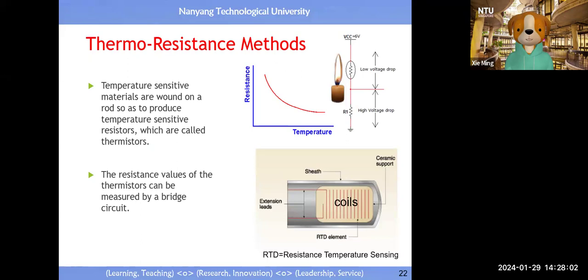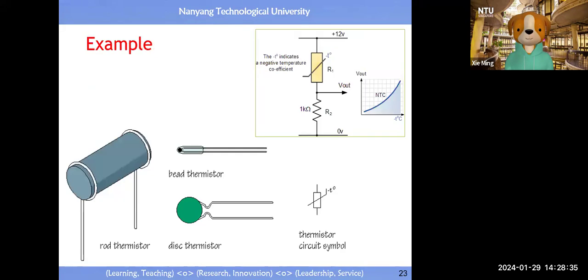So in the video, the very popular one should be the resistor. So we have a special type of resistor. Resistance is a function of temperature, and we give this device the name thermistor, the thermal resistor, right? And in the video you see the popular type is this NTC thermistor, right? So when temperature increases, the resistance value will decrease, right? And in the market you can buy a lot of such resistors. Then how to